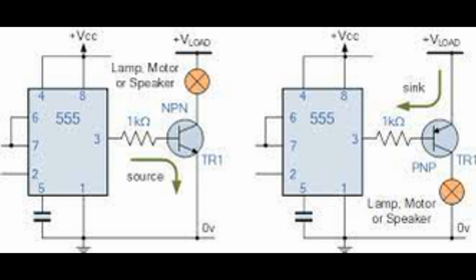Astable operation is when the output voltage rises and falls in a set pattern, making it an oscillator. As the pattern can be varied, it can be used for any purpose which requires a particular tone pattern. Bistable operation is when the signal can be held in one of 2 positions, meaning the 555 timer can act as the smallest possible unit of computer memory.